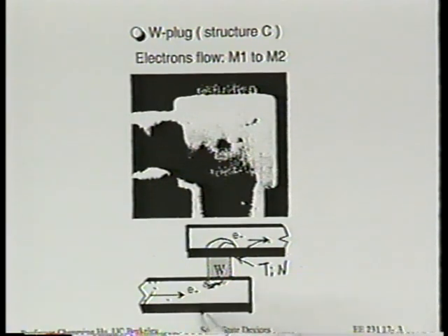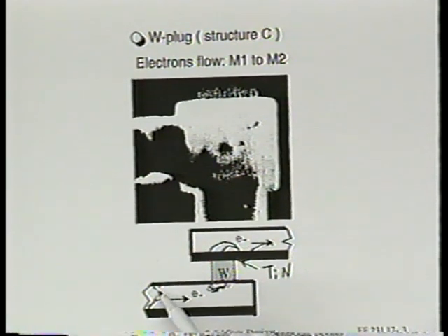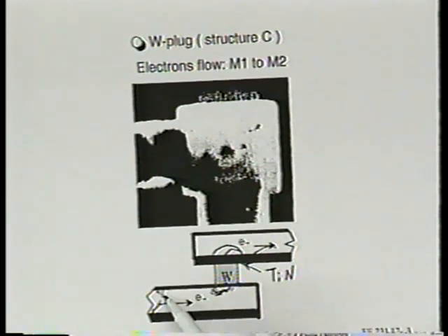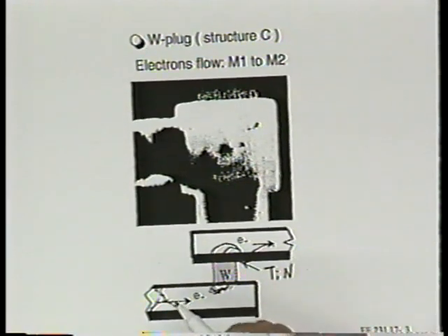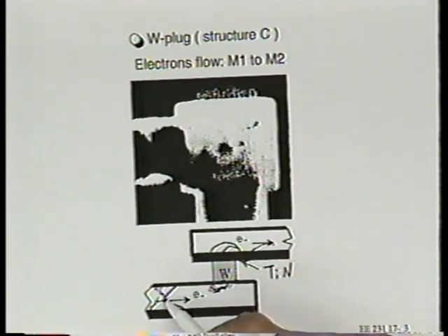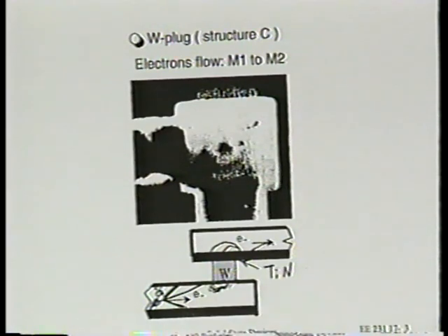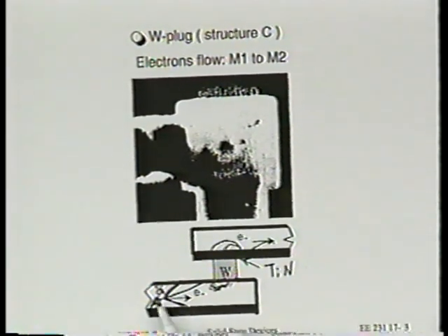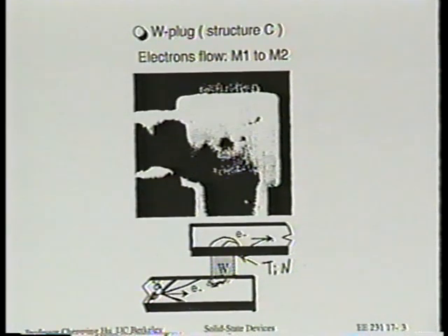This is because in the long line, the electromigration happens mostly at grain boundaries. Mobility of the aluminum is much larger in the grain boundary compared to the bulk of the grain. So suppose you have a particular point where you have several grain boundaries moving away along the direction of electron flow, and you only have one grain coming in, or there's no grain coming in, like in this case. You have several grain boundaries going away. Then there's very little supply of aluminum toward this point. We call this a triple point. But there are several paths to take aluminum away from this point, right? By electromigration.